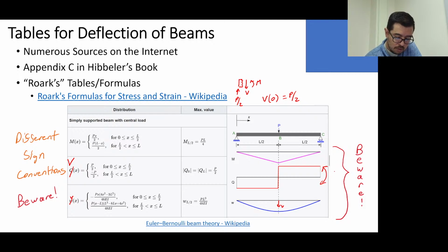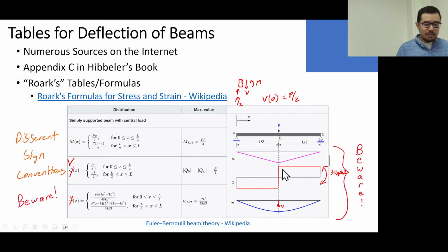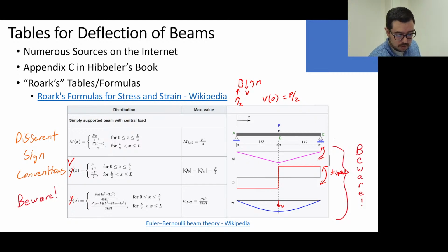Okay, so it's flipped, using a different convention than we've been using in the class. And the moment, remember what we said at the beginning yesterday? Positive moment is positive curvature. So we don't even have to do any of the math. This is negative moment, and we know this is going to have a positive curvature. So this is also flipped. Any questions on that?